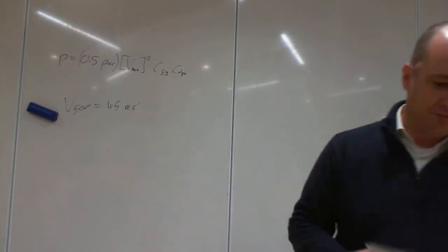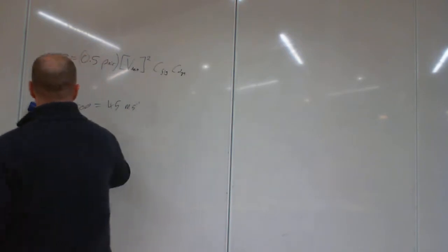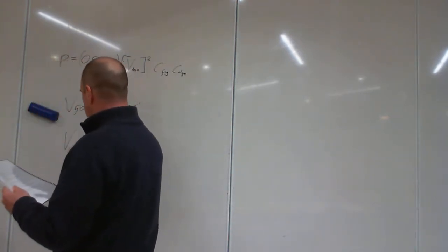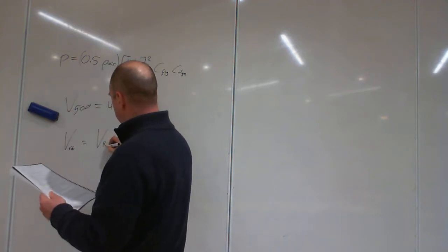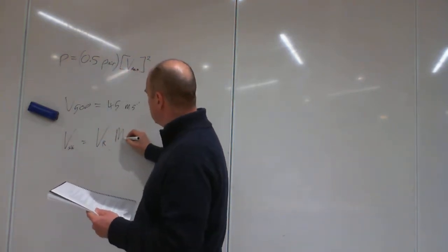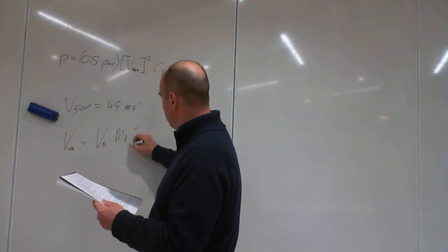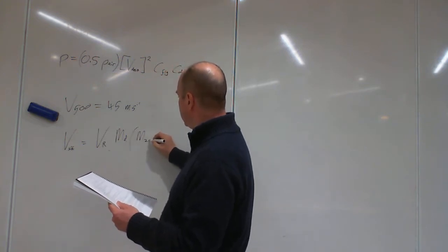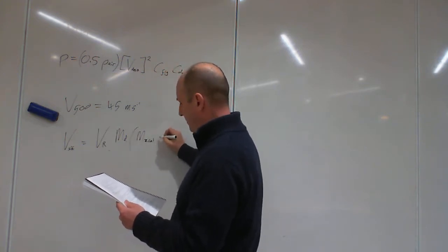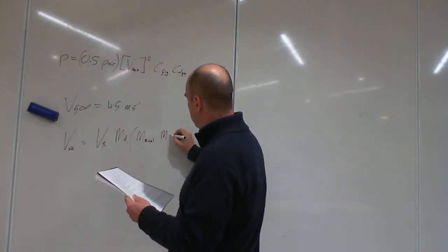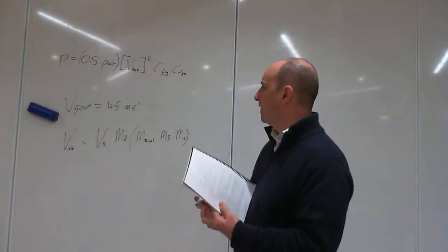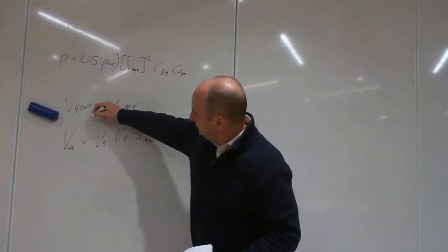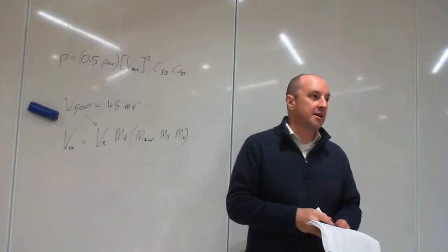Now, our wind speed, there's an equation here, which is wind speed is, here we go. Our design wind speed for our site is going to equal VR times MD times MZ,cat times MS times MT. All right? That's VR, we've done that one already.